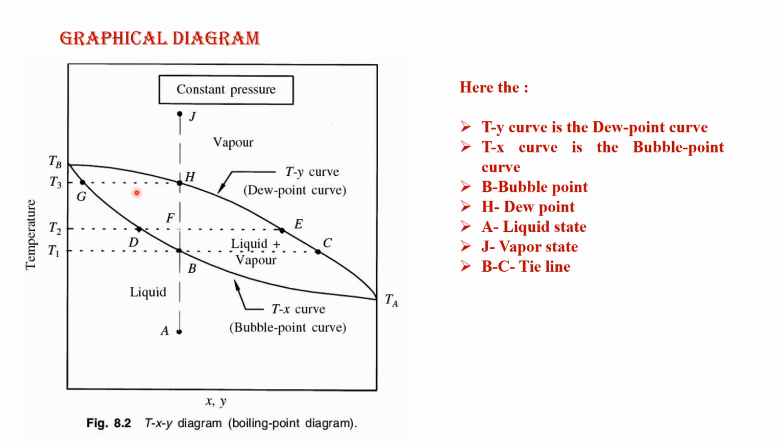Since the vapor phase is not removed from the system, the composition of the original mixture is equal to the composition of the combined mixture, because we didn't remove any vapor from the system till now. That's why the composition is not changed, but the relative amount of the liquid and vapor is changed, because we kept the pressure constant and not the temperature. So the relative amount depends on the temperature only. If the temperature increases, the relative amount changes.